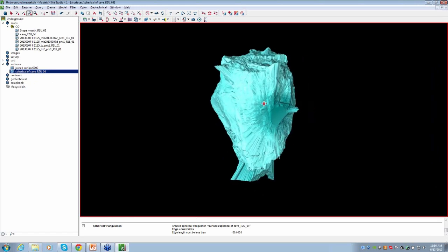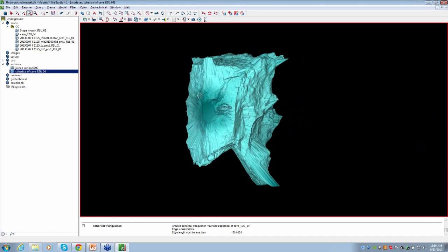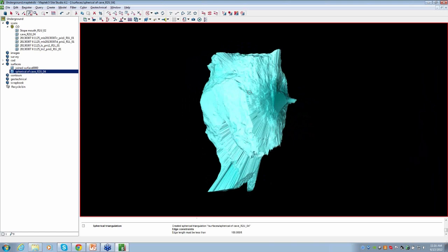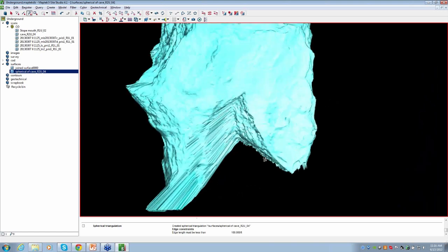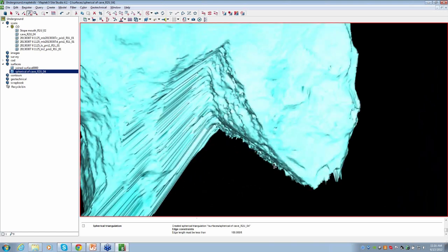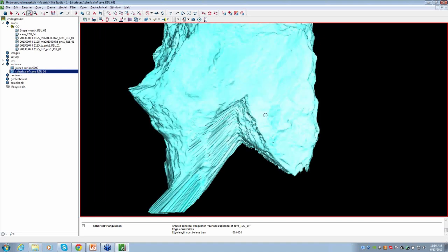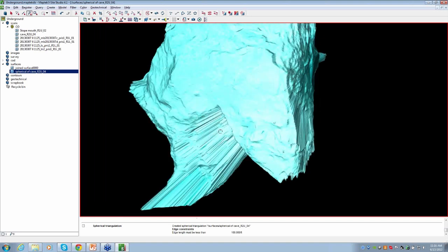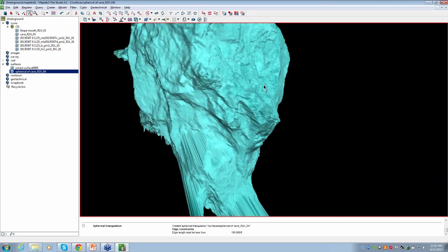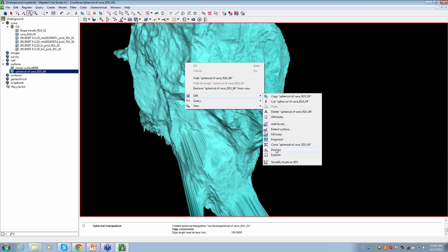And we can still utilize all of the other tools in the software to clean this up a bit. So like down here you may notice there's some spikes and points from just some of the more jagged rocks. And just to make this a little bit cleaner, I'm going to go ahead and run a D-spike on this.